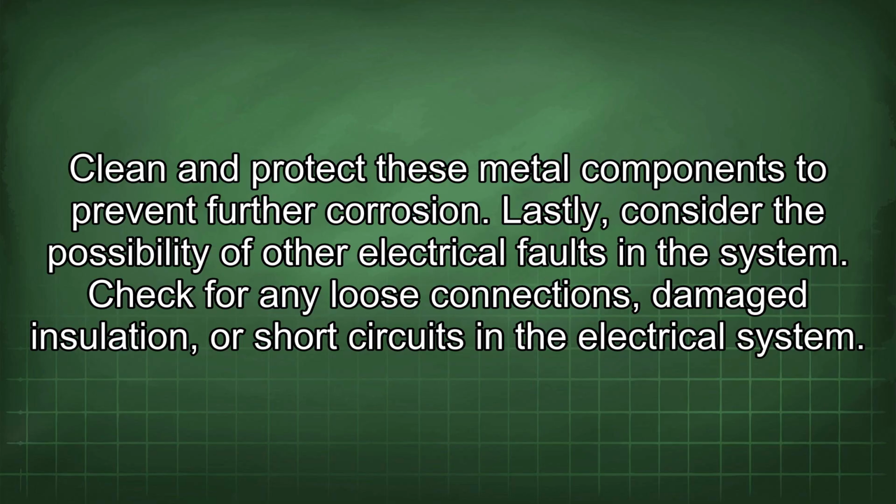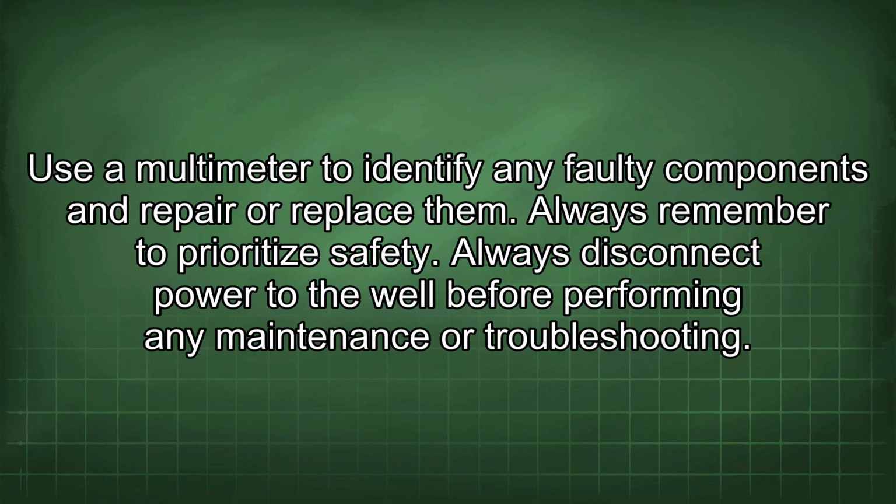Lastly, consider the possibility of other electrical faults in the system. Check for any loose connections, damaged insulation, or short circuits in the electrical system. Use a multimeter to identify any faulty components and repair or replace them.